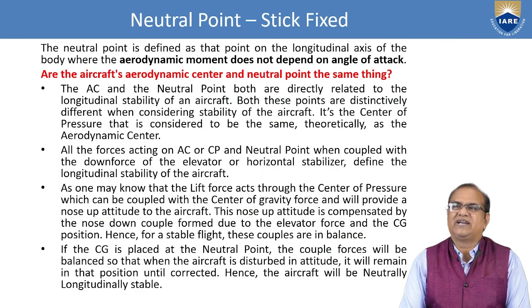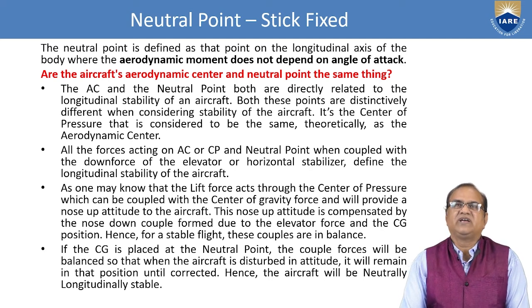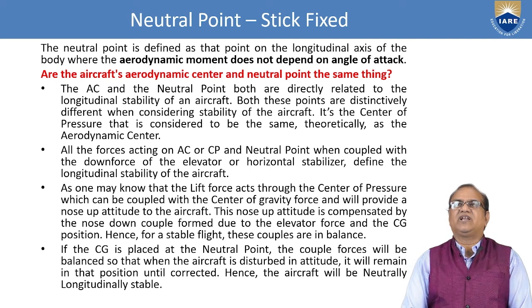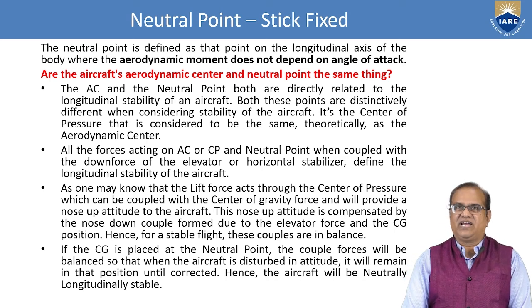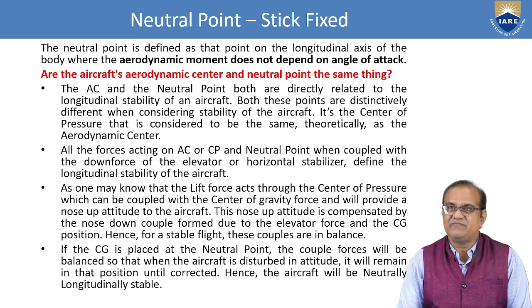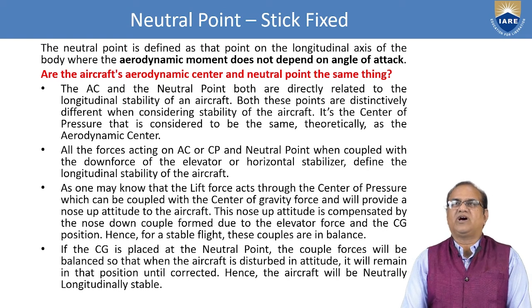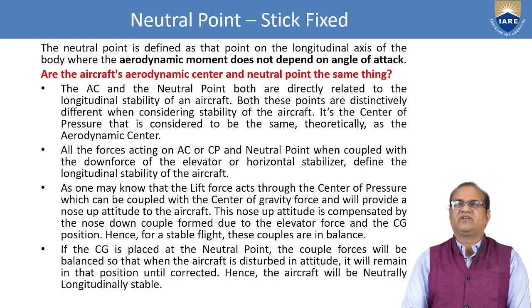Further, I am going to discuss the neutral point, stick fixed. The neutral point is defined as that point on the longitudinal axis of the body where the aerodynamic moment does not depend upon the angle of attack, or the aircraft aerodynamic center and the neutral point are the same. The aerodynamic center and the neutral point are both directly related to the longitudinal stability of an aircraft.